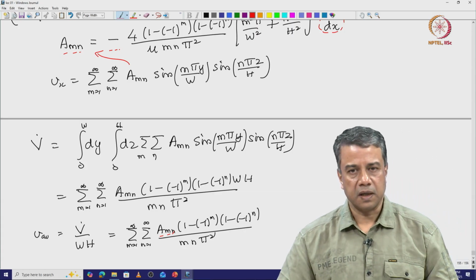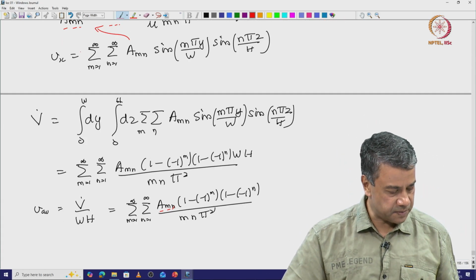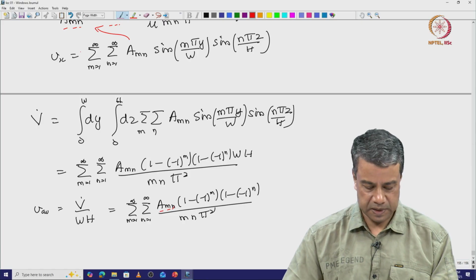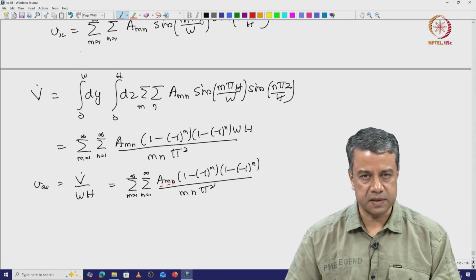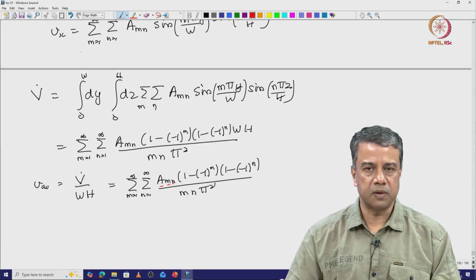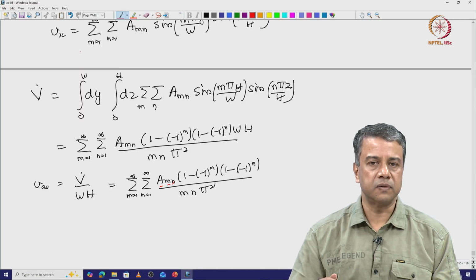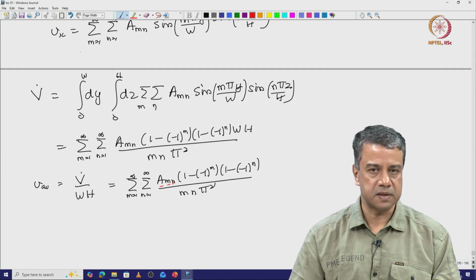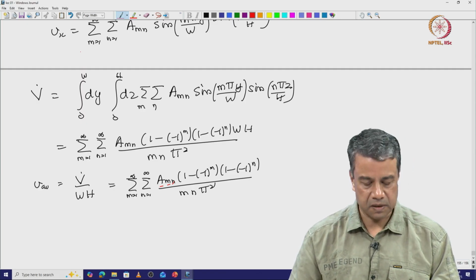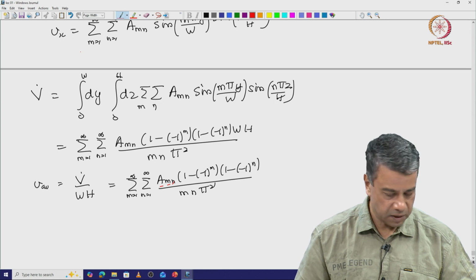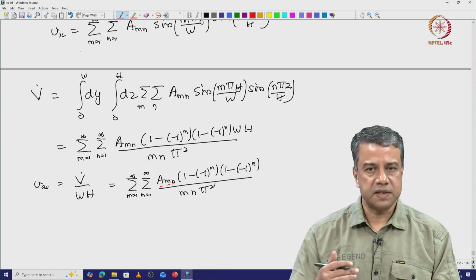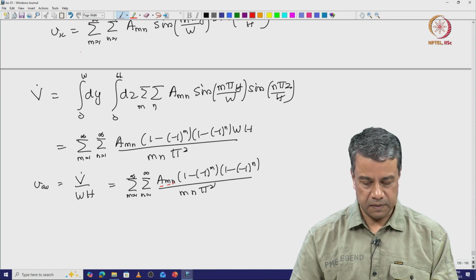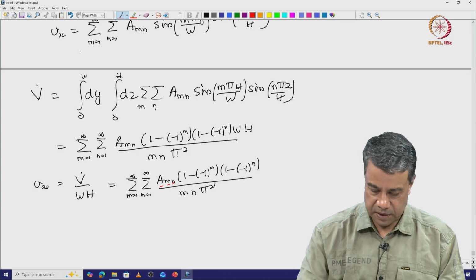And you can do a series expansion, you can include a finite number of terms and actually evaluate what this is. So, usually up to about 5 terms is sufficient to give you an accurate result for the average velocity up to 2 decimal places. So, you can use a truncation of this expression. I am sorry, there should be a dP by dx here.